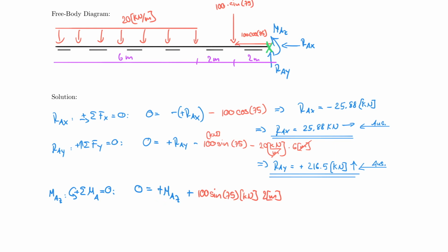All right. So now I can use my other force, which is also positive. 20 kilonewton per meter multiplied by 6 meters. And now comes the trick, which is not a trick really once you understand it, but you know that the lumped force acts here, so at 3 meters and 3 meters, and we need to take the sum of the moments about this point.